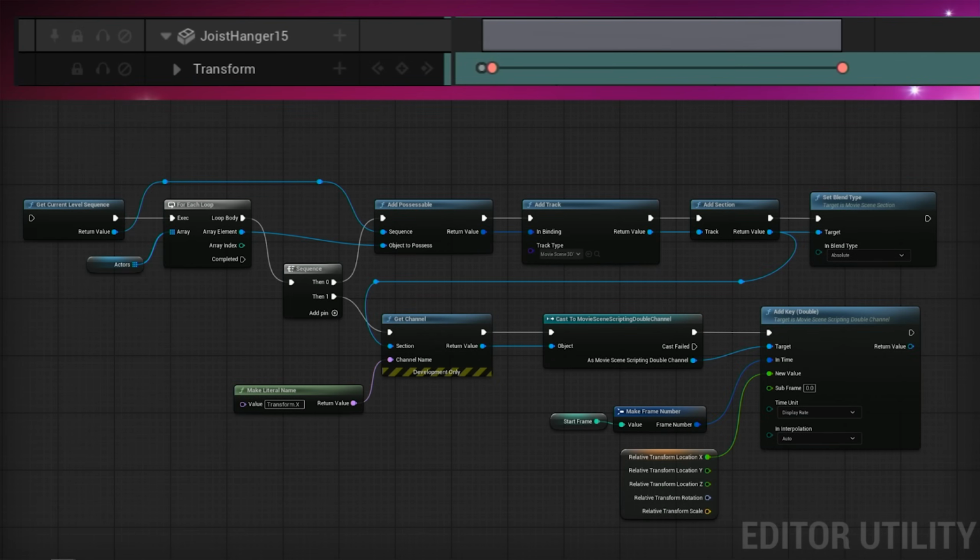And if you can't read that, don't worry, it might not even work if you copy-pasted it. But I just wanted to summarize my method for procedurally animating this in Unreal. If you've ever done sequencer animation in Unreal, hopefully you found it somewhat simple. You have your sequence, you drag your mesh into the sequence, you click the keyframe on the transform track, and that's your animation. If you want to script it out, it actually gets a little bit more complex, which I learned the hard way, so I just wanted to clue you in if you wanted to do this yourself.